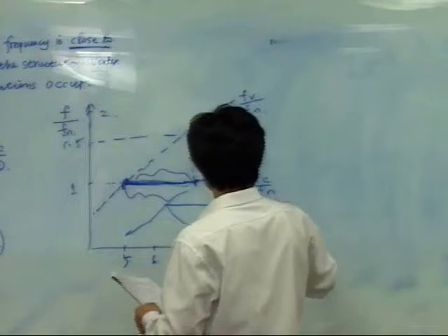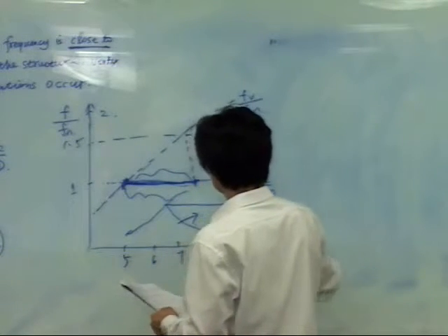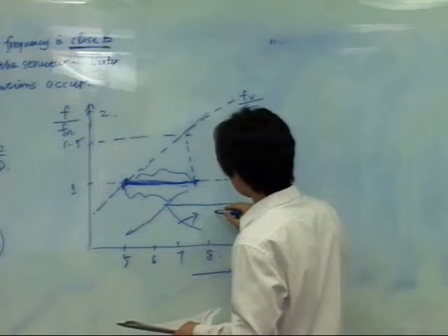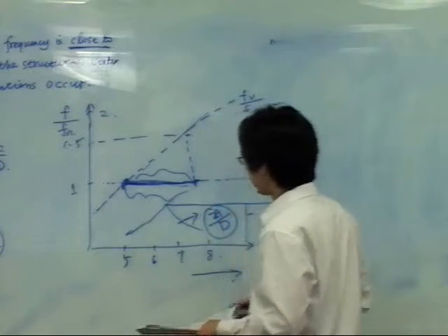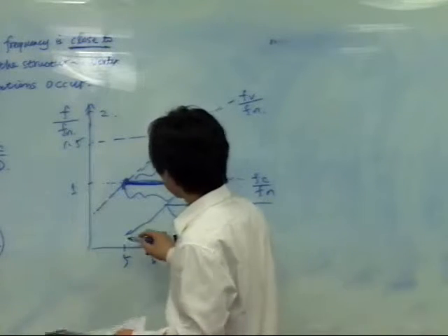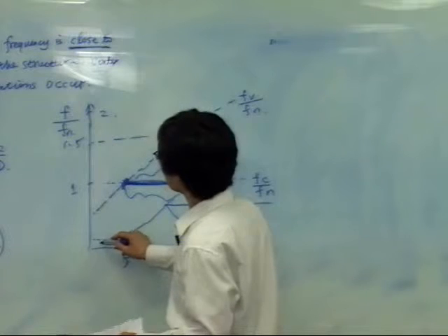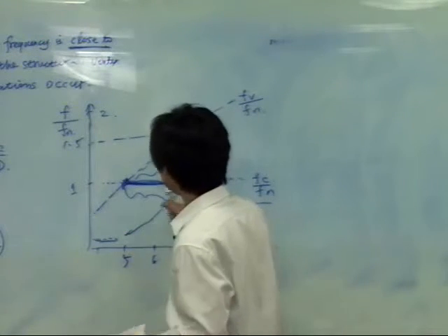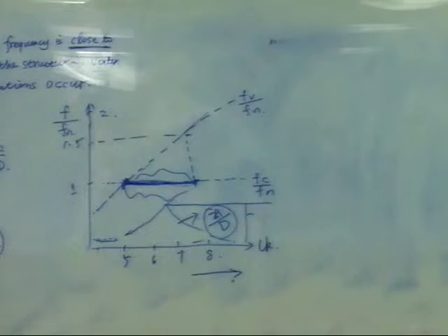This parameter is the RAO, the oscillation amplitude over the diameter. This is for illustration only, right? In this range. But outside this range, with non-resonant oscillation, the amplitude would be very small. However, in this locked-in region, it's very, very large.